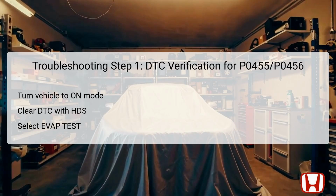This action resets the system states and allows you to get a fresh snapshot of the vehicle's current condition. Subsequently, select the EVAP test option from the HDS inspection menu, followed by the function test. Assessing the results from the EVAP test will help confirm whether the DTC is persistent or intermittent, guiding subsequent steps